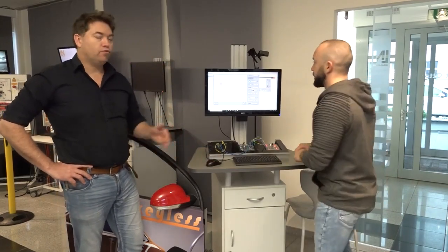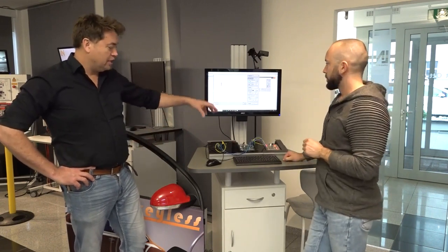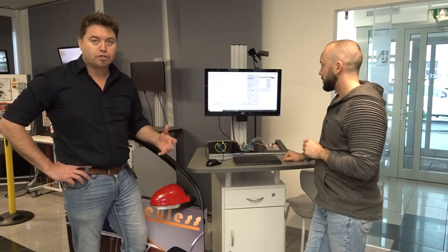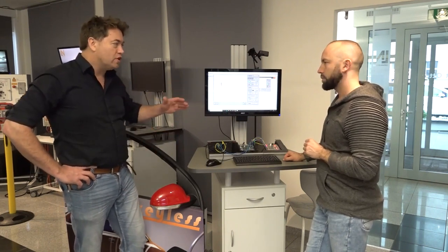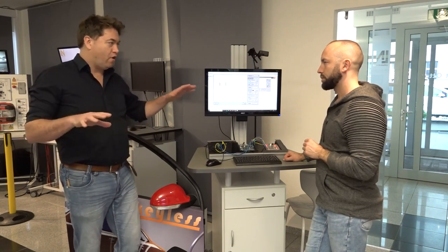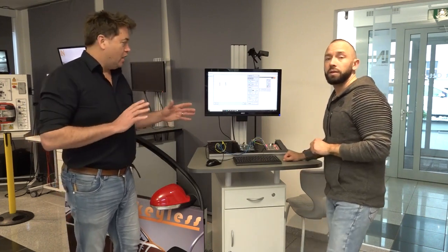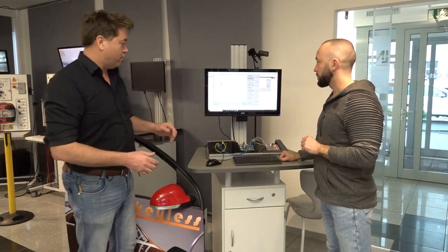And that's what we were saying before about the processing power to do this. It needs bigger processors, better processors, more expensive processors. Modern vehicles, I think a lot of them have started to go to a single bus speed, so 500 something like that, yes. Yeah. Megabits per second. Not all vehicles; obviously older vehicles have a mixture of these different speeds that you'll find on there.